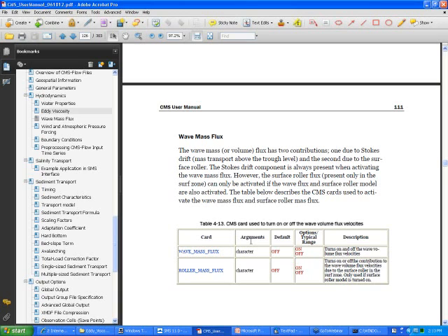So if you go to the field and you put an instrument in the surf zone, that's what you would see. You would see a component going offshore due to the undertow. And if you don't use the wave average formulation, then the currents will just be parallel to shore.